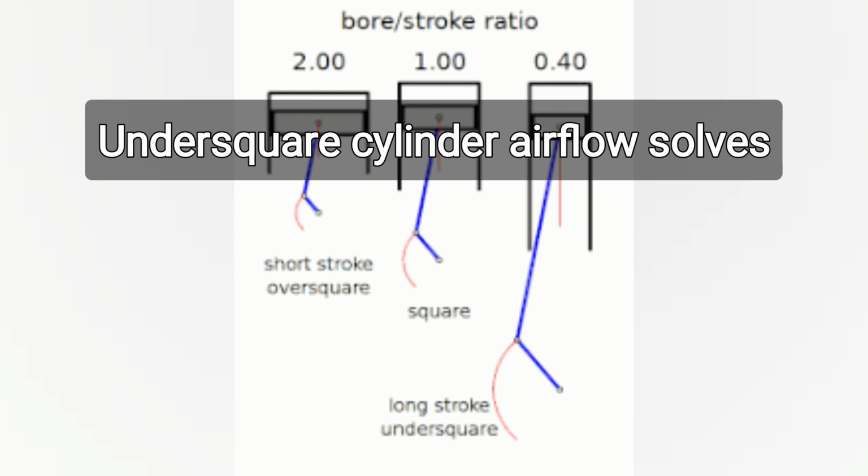And with a little bit of gasket material right there, that valve has a very easy way of having fluid come in and go out, and it also has an ability to handle much higher pressures, because the head becomes a structural part to that little gasket-ish outcropping area. It seals in, and that helps also with engine coolant and oil, as I can route it around and still take that heat from that lubricant away as a heat exchanger.